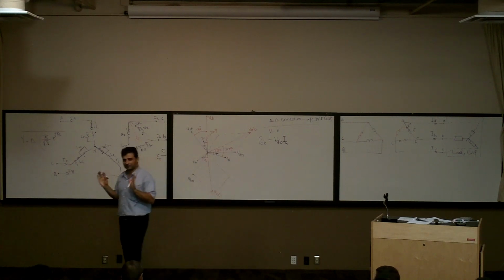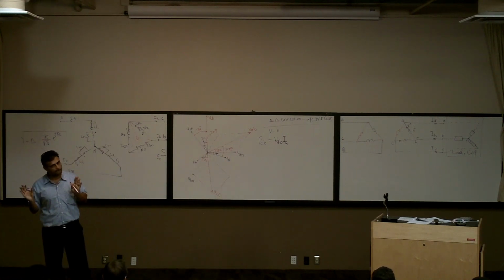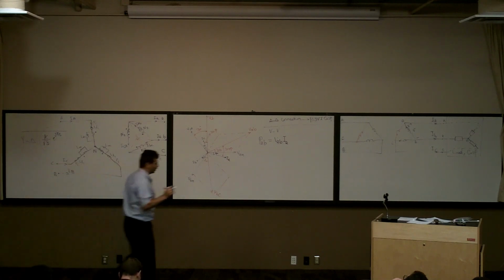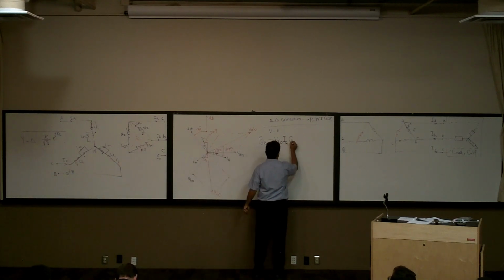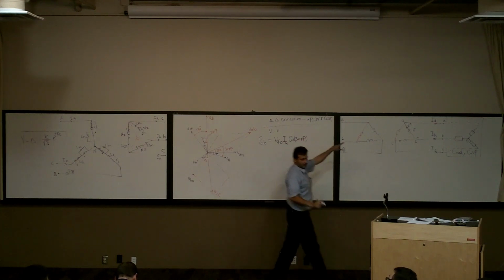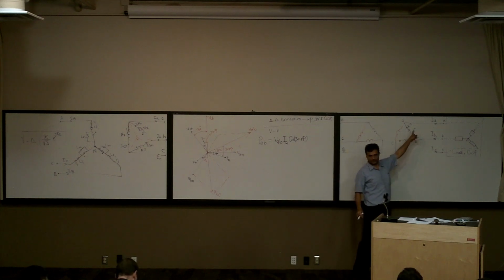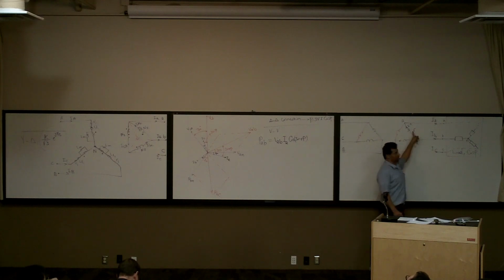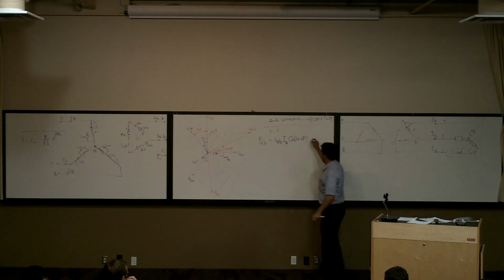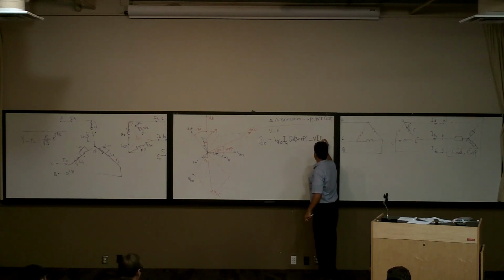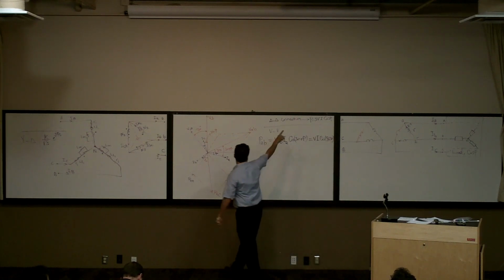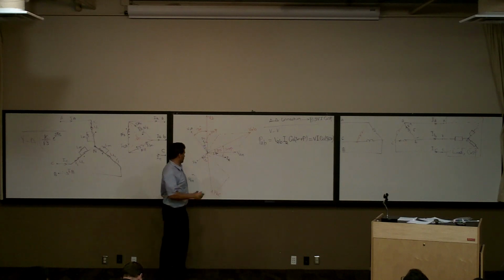How much is the angle between VAB and IA? 30 plus phi. So it's going to be the cosine of 30 plus phi. How much was the VAB? Nominal V. How much was IAB? In this case, IA and IAB are the same. How much was the nominal current for this winding? I. Basically, this one is going to be VI cosine of phi plus 30. I'm going to compare it with the top one over. Now tell me how much is the PCB.